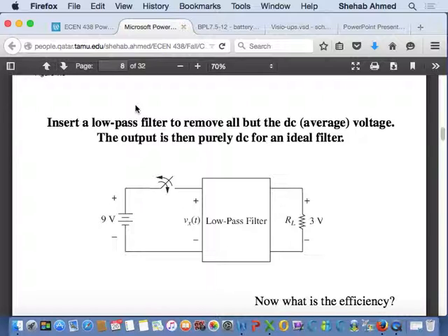Okay, this is the output. This is the system. What do I want it to do? Something else. Okay, so how about giving it a push in one direction? So the controller will change the duty ratio to push it in the right direction. Push the system, whose transfer function you've derived in 214. That transfer function can be a circuit, or a motor, or something else, a full power system. So that's the 420 class. In here, what you did in 214 for linear circuits, we will do for power supplies as well. We will make the power supply look like a linear circuit and derive its transfer function.